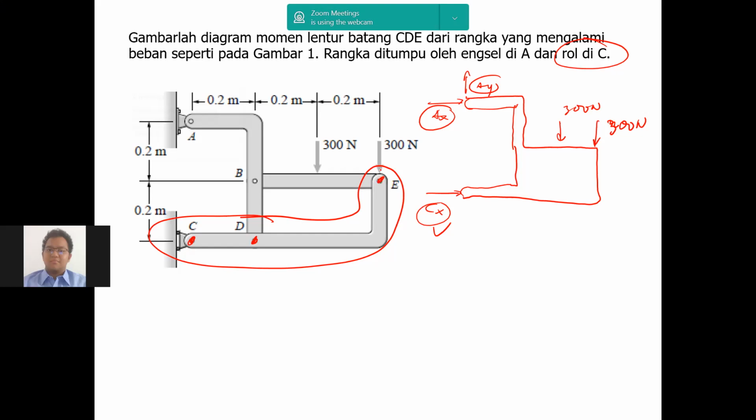Correct. So in order to solve for the internal moment and internal force diagram, like it or not, we have to solve for those joints, right, Aditya? Yes. We have to know the forces happening at D and at E as well, because up until now we just found the forces at C. So we have to find this and this. That's our aim in the frame problem.